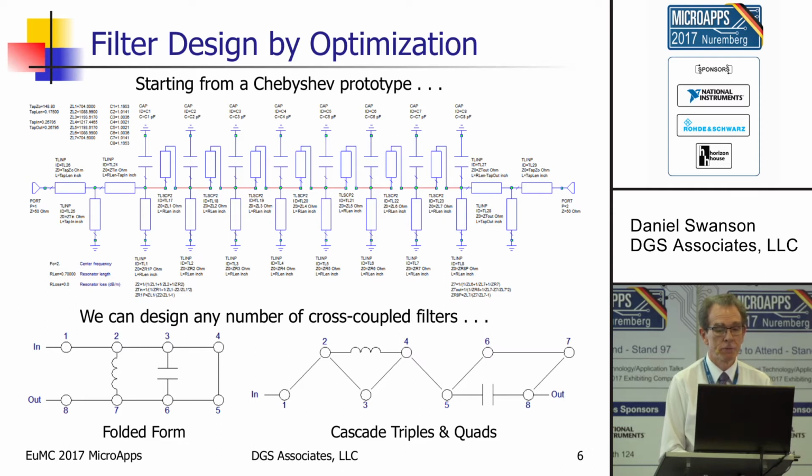This is a correction factor for the tap added by Crystal. And if you could see it, it's fairly high impedance, and it's actually a negative impedance. And our tap line is out here with a known impedance and a known length. So this is as close as we can get, basically, to reality.